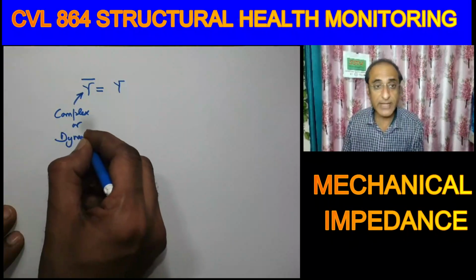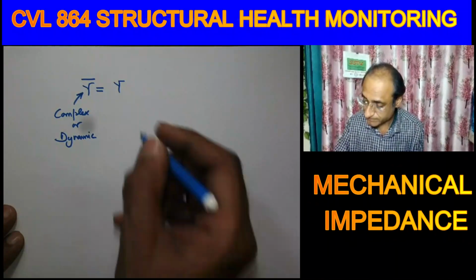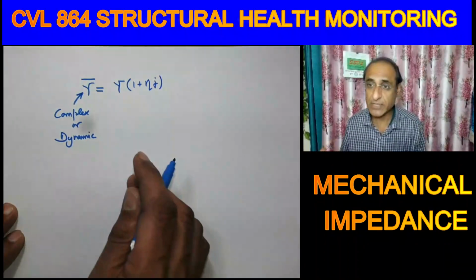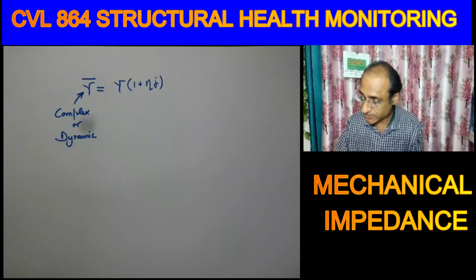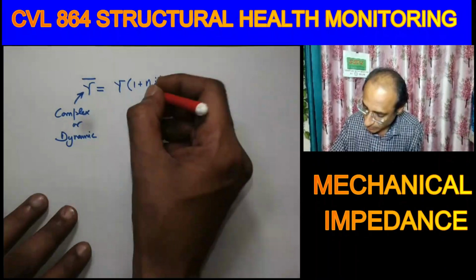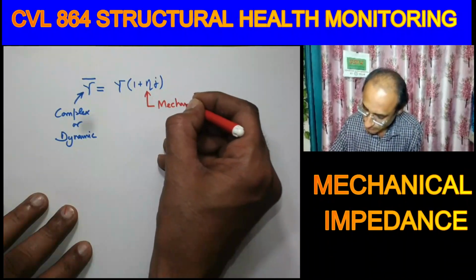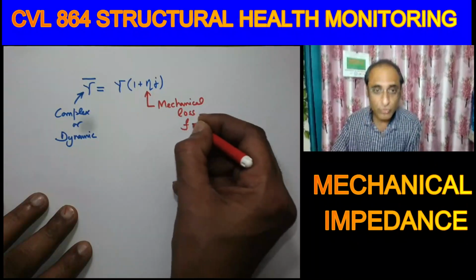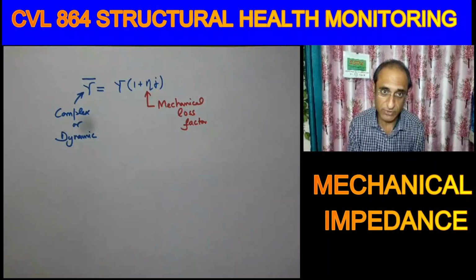So in all our derivations, whenever we have a term with a bar, it means that it's dynamic. And naturally, you know that the dynamic Young's modulus is higher than the static Young's modulus. So it's this factor, the mechanical loss factor, that leads to a higher value of the complex or dynamic Young's modulus, right?